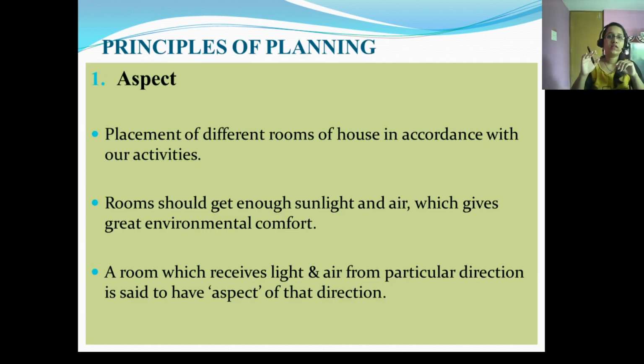Aspect means the peculiarity of the arrangement of doors and windows to the external wall of a building, which allows the occupant to enjoy the natural gifts such as sunshine and breeze. A good aspect is desirable as it provides comfortable conditions and a cheerful atmosphere due to proper sunshine and breeze. It also gives better hygiene conditions as the sun rays are potential destroyers of organic poisons. It improves the external appearance of the building due to proper location of doors and windows.